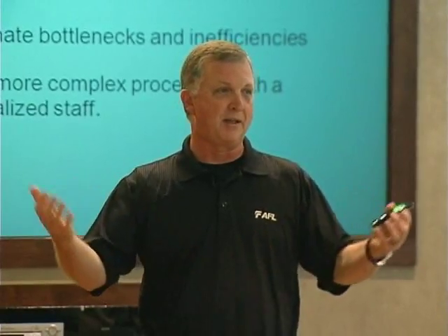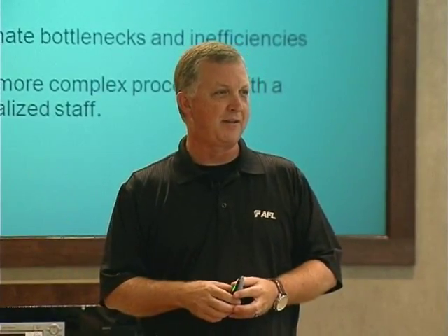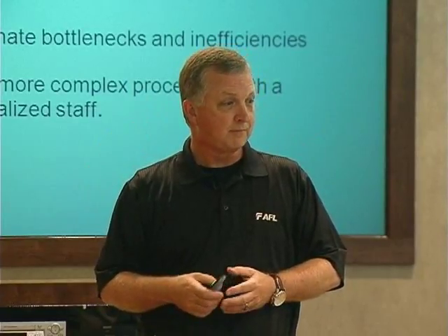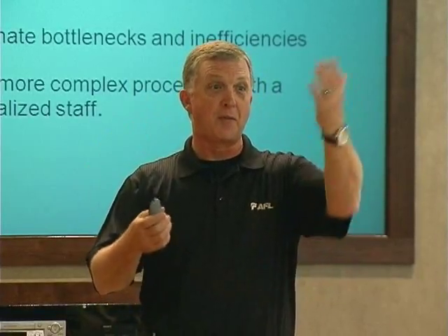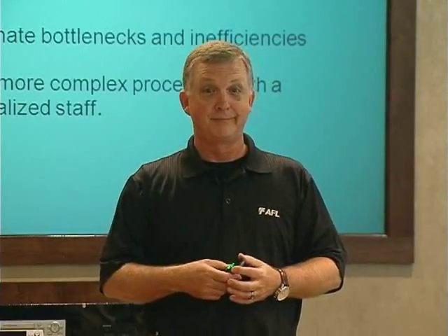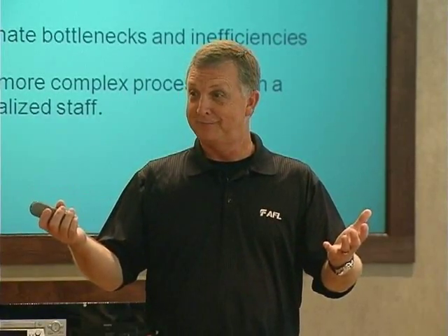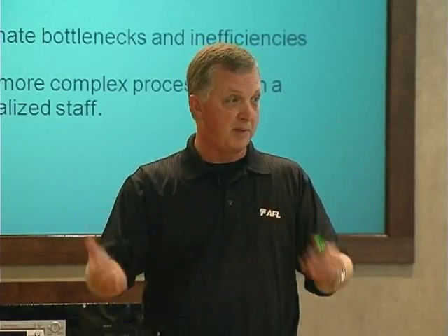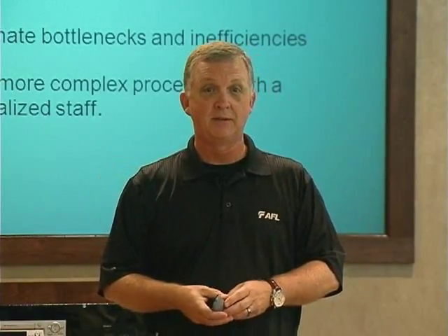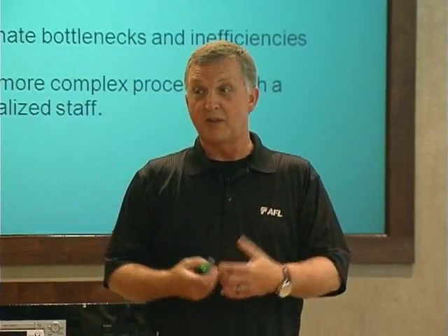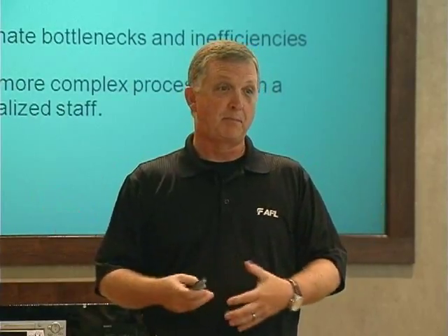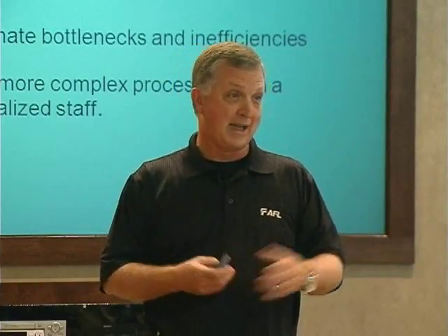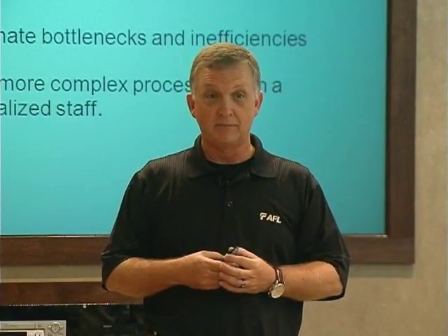What's some more simple things? I mean, maybe just kind of thinking, going over the simple stuff. I want to know if the power's on, or where is it off. All right, so I can do that in a lot of different ways with this type of system, with the meters or with the devices I put out there. I want to know what the voltage is. If it's supposed to be 12 kV on this distribution line, I'd like to know that it's actually 12 kV.